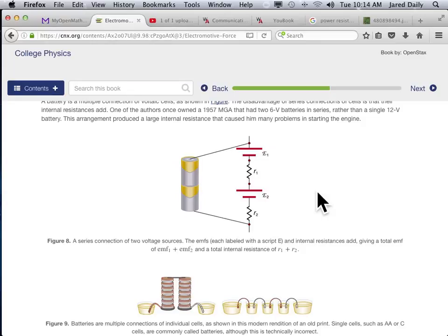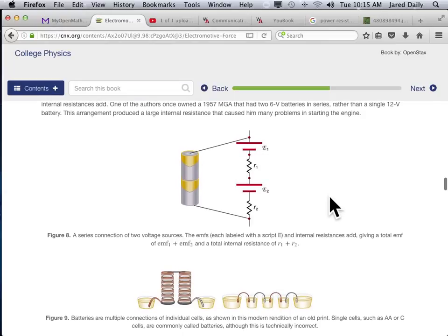And you have lead oxide mixed with acids and all kinds of other things. And then you just create new anodes, and then you take all the acids out of the battery and put them through a chemical process, and you separate out the impurities and make the acid again that you need, and put it all back together. In theory, it's a simple thing. In practice, it's messy, it's dangerous.